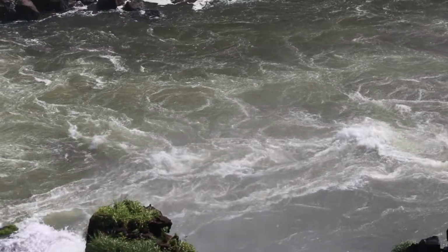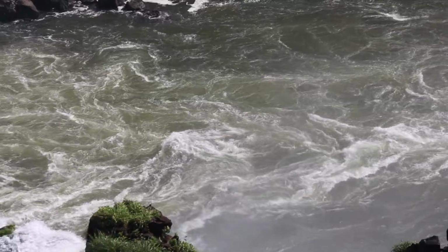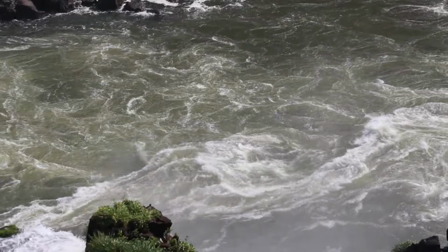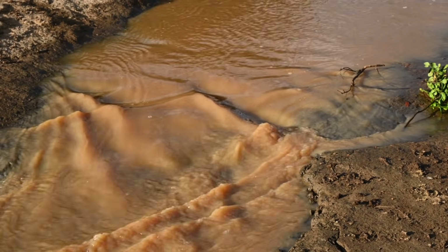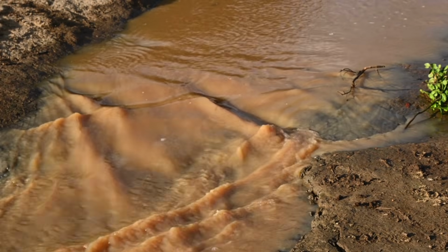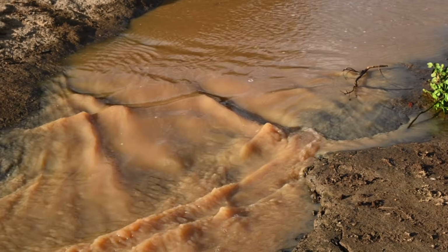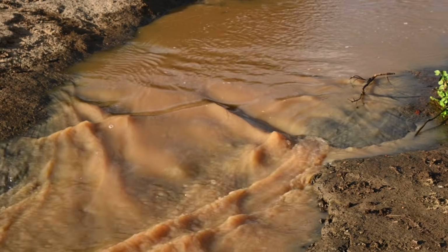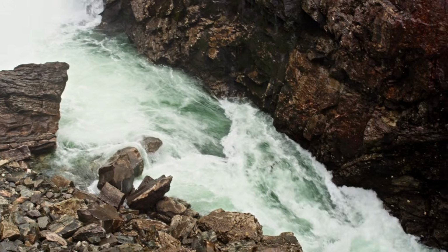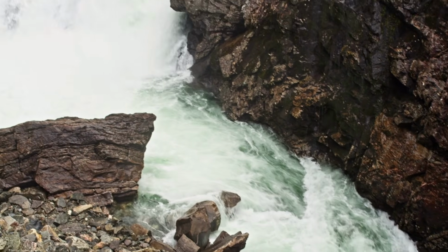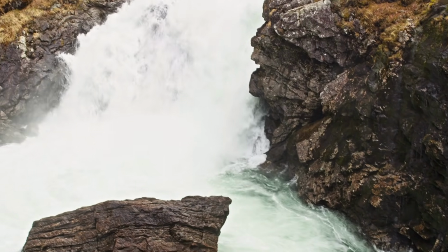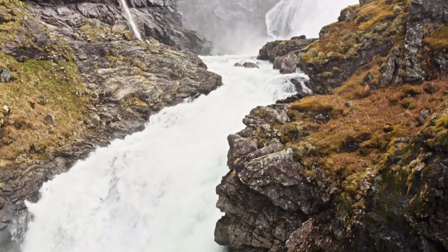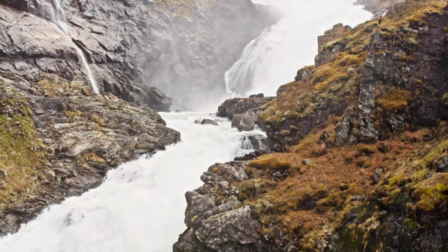In a wet bed scenario, the resistance is lower because the water is essentially sliding over other water. This allows the surge to maintain its height for much longer distances. Scientists use the Froude number to describe this state. It is a ratio of the flow inertia to the gravitational force. When the Froude number exceeds 1, the flow is supercritical. This means the water is moving faster than the waves that would normally ripple across its surface.